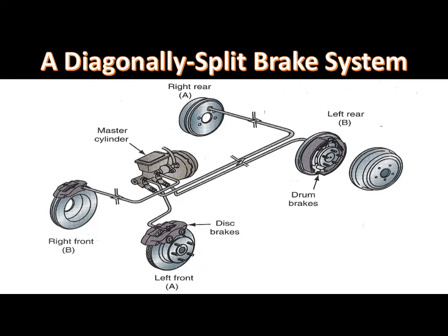When the brake pedal is depressed, the primary piston moves down the master cylinder bore and the primary cup seals the vent port. This action seals the primary piston cylinder and forces fluid from the primary outlet ports. Pressure in the primary bore moves the secondary piston down its bore, and the vent port is sealed by the secondary piston cup.